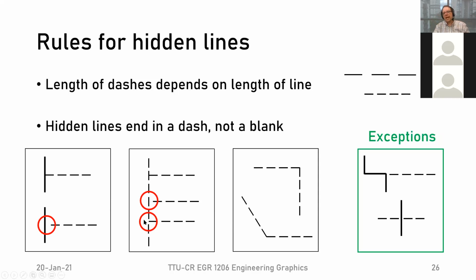Again, if you do this by hand, sometimes that gets a little tricky. You might have to erase your dashes and redraw them, because you drew a dashed line for a hidden line, then you notice that the second one that intersects runs into this problem right here, where you drew this line first, and then you're drawing this extra line, and it hits an empty spot. But you'll figure that out.